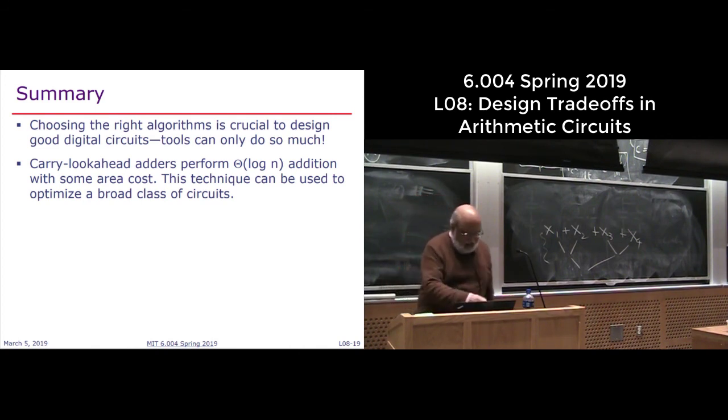And the last point is, carry-lookahead adders perform order of log n addition with some area cost. The technique can be used to optimize a broad class of circuits. Please study this, right? If we haven't asked you to implement it yet in the lab, you will definitely need it for the project. So any effort you spend in trying to understand this will not be wasted. Thank you.